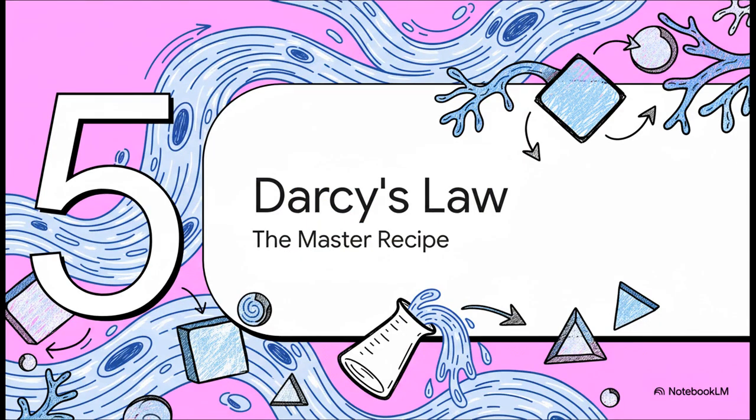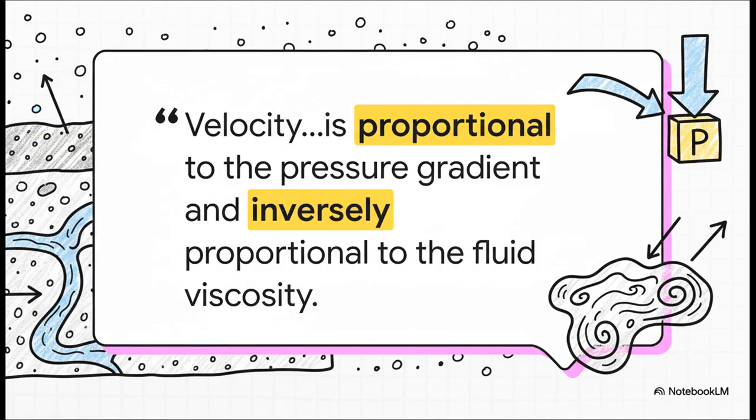Okay, so we've got the fluid type, we have its flow over time, and we know its geometry. So how do we pull all these ingredients together into one single, powerful recipe that describes this whole process? Well, the answer is Darcy's Law, something figured out way back in 1856. And at its core, it's a surprisingly simple and intuitive idea. It basically says the speed of the flow depends on just two things: how hard you're pushing it and how easily the rock lets it through.